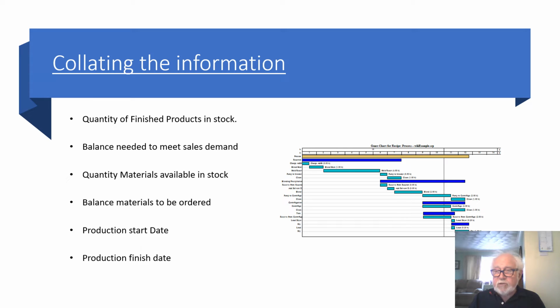To enable accurate planning, you need to ensure that material lead times are correct, production equipment and machinery is available, and speeds and feeds for machines are correct. You should check if there are any bottlenecks in the production process and that times allowed are accurate for all manufacturing processes and quality control checks.